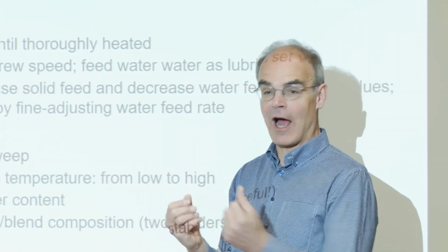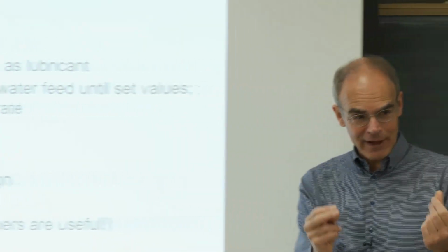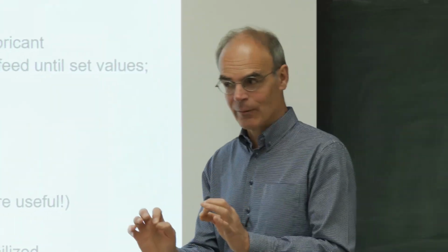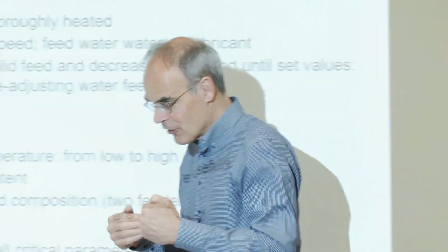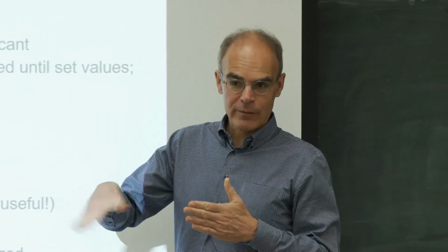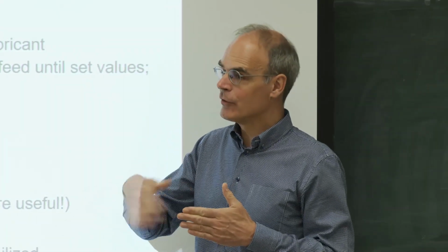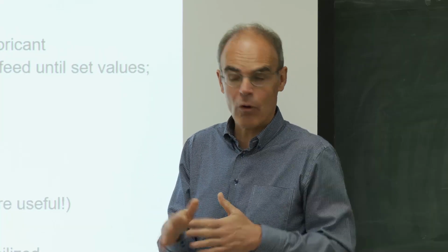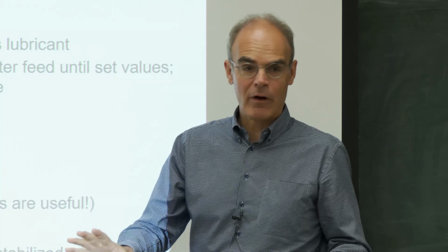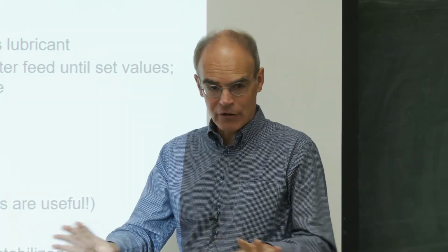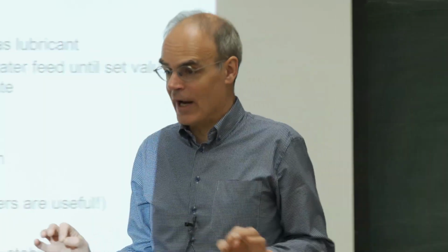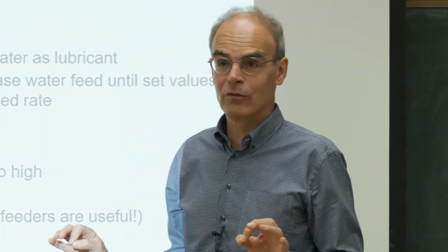You can do it, but I love the phase because you have to play a little bit with the extruder. Then sometimes say, let's increase the screw speed a little bit. You have to be very careful, in some steps. You can actually get all that solid material out of your barrel, and at some moment you run it again with clean water, almost clean water. Then you can shut it down, cool down your whole barrel, make sure that really the pressure is gone. And then if you take your screws out, you will see your screws are 80% clean. So way less work to clean it.